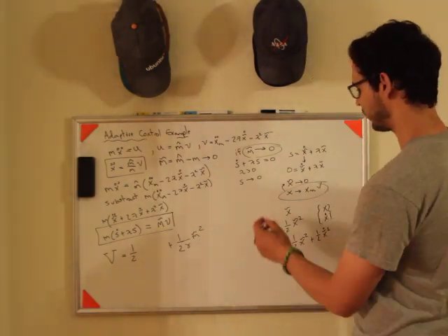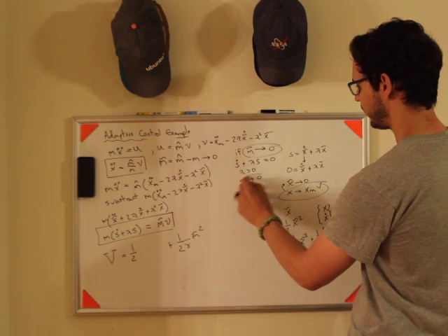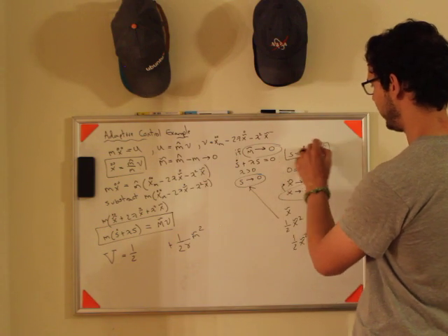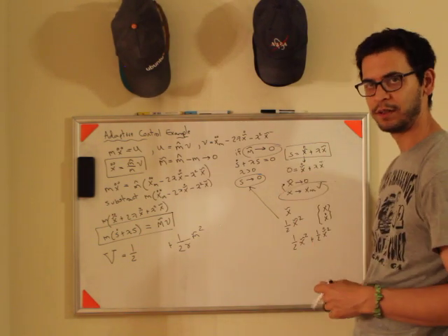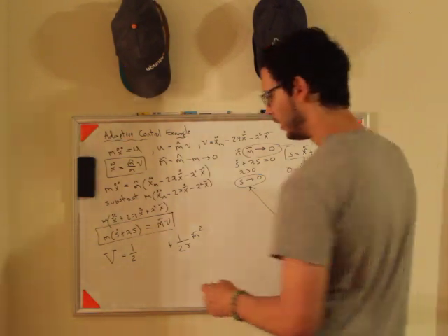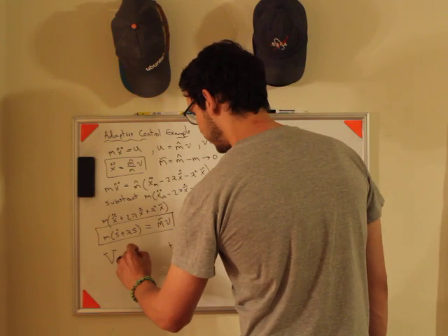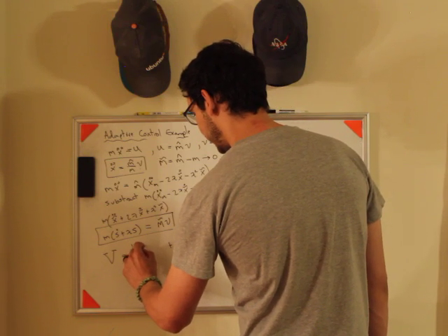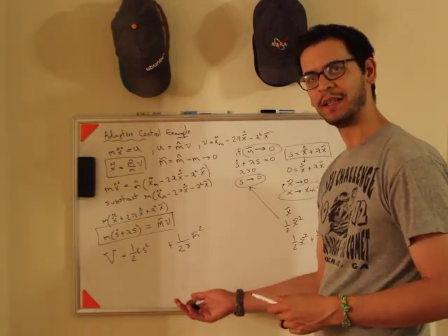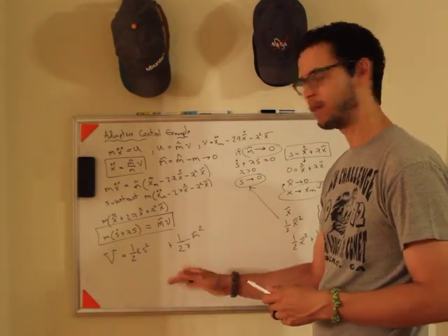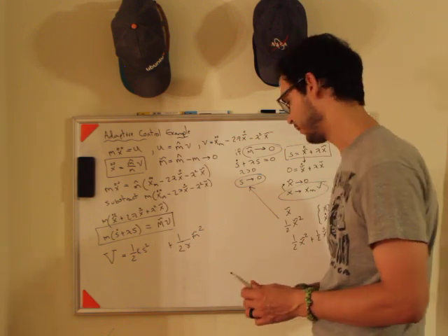The better thing is really just to use s, right? s is equal to x tilde dot plus lambda x tilde. So if s goes to 0, the other two go to 0 as well. So then I'm just going to do 1/2 k s squared, okay? Now the k, I could plug in what it is, but I'm going to leave it blank for now. You'll see how it shakes out in a second, okay?